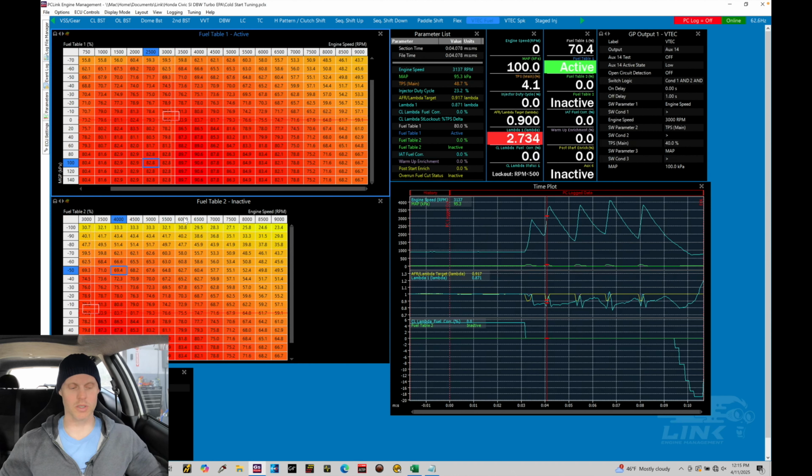Now, one other thing I'm going to do is, we know that our torque curve was rolling off on high cam, or I'm sorry, on low cam. That's because we were in low cam, not VTEC. With VTEC engaged, we're going to be able to carry the power band much higher. Therefore, our torque curve is going to be going much further and broader, and we're going to carry power to...